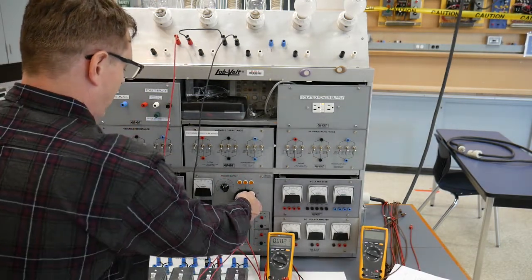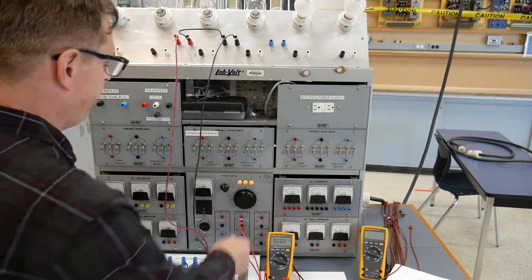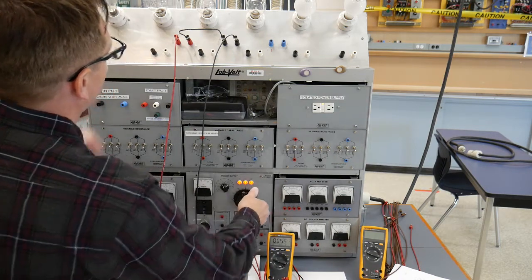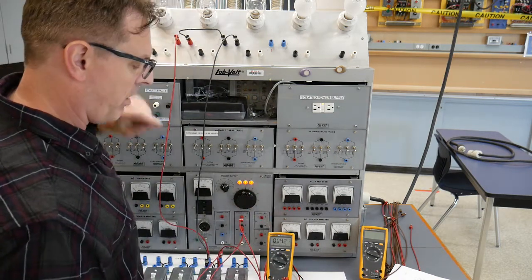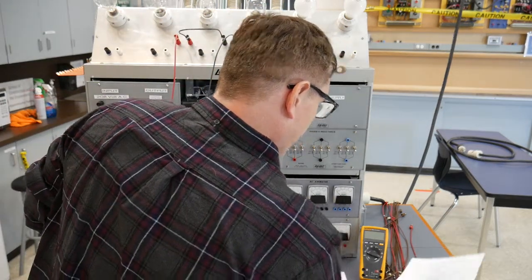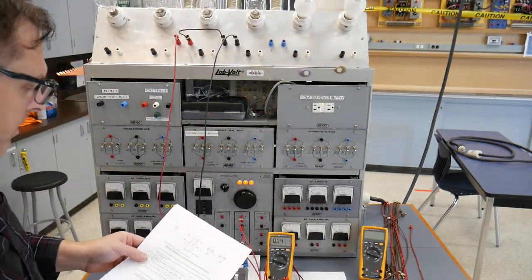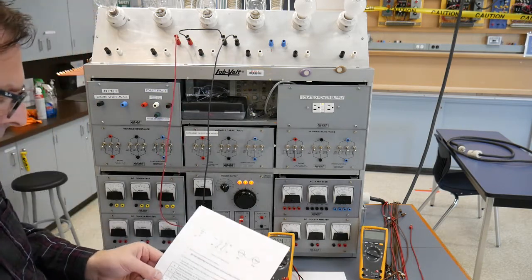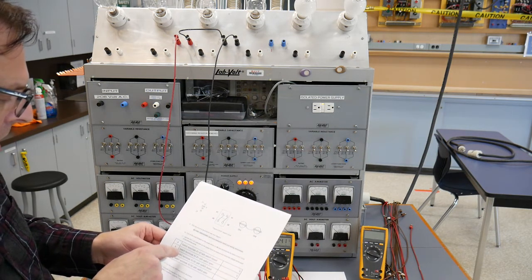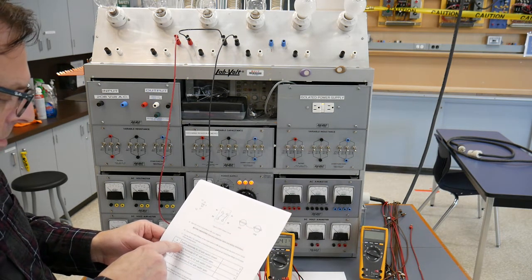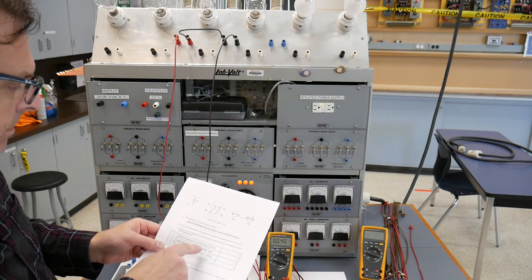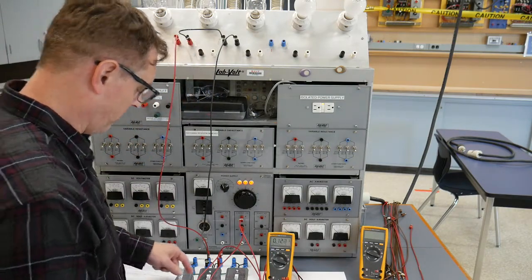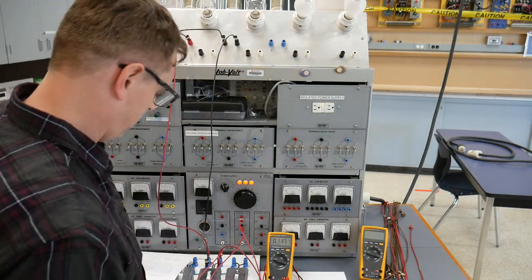All right, I'm going to turn the power on and energize slowly, just to make sure nothing blows up on us. And we're good. Those cone heaters should be heating up, which they are. They've labeled the A's and B's here on this guy. So our A's are across the top, our B's are across the bottom. Now they want us to measure the voltage between the switch terminals A1 and B1. That would be the output side here. We're going to measure there with the switch closed, which it's closed right now.